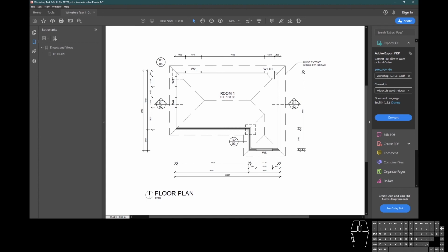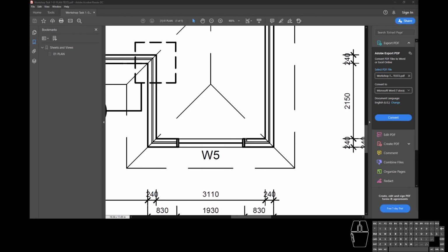Printing it really is the only way that I'm going to know how that's going to look, and it can be super important. As an example, I've beefed up my window frames here because I think they look really good when I'm zooming in. However, if I printed this, I might not be able to see this difference. They might really meld together, and what I might need to be doing is actually putting that back down to that yellow line weight to be able to see that line work. The only way that I would know that is if I did a test print. And that's why it's important to know the difference between plotting and printing.